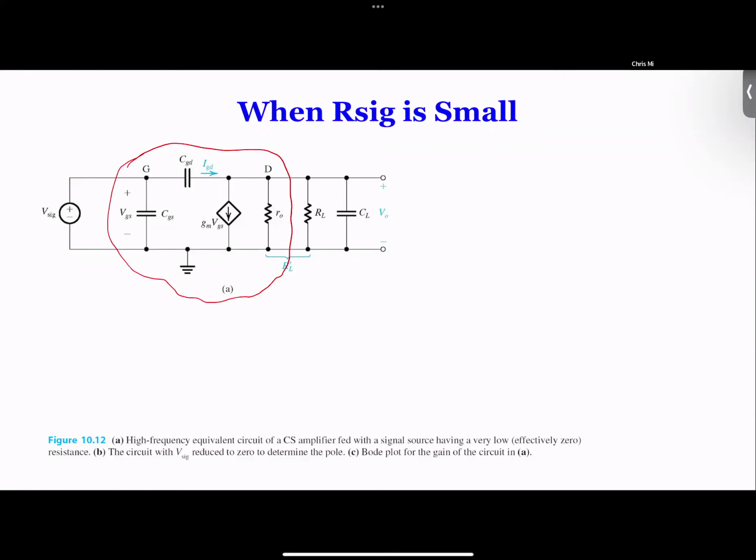The reason we put CL is that CL often represents what we call a parasitic capacitance of the output. Normally, this CL is negligible. But for small signals at high frequency, this CL sometimes becomes significant. We cannot neglect it. It's parasitic. For example, you have a resistor, and on the resistor you have input and output, and between this input and output there's capacitance. The capacitance is so small that we normally wouldn't bother about it. But in the high frequency response, we have to consider it. Okay, so CL is here.